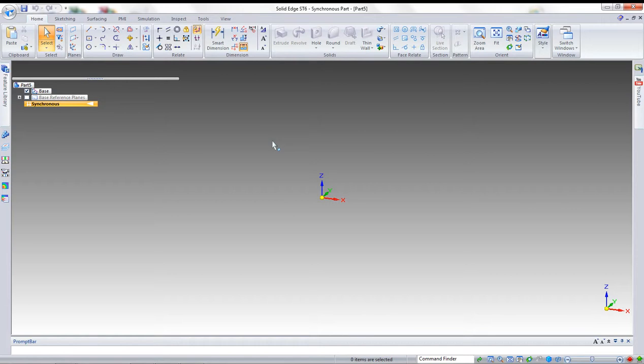Whenever you go to flatten a part, that would give you an orientation for your flat pattern that easily matches up with your CNC. Same thing goes with blocks of metal that you might be milling, or whatever manufacturing processes that you have on your shop floor.